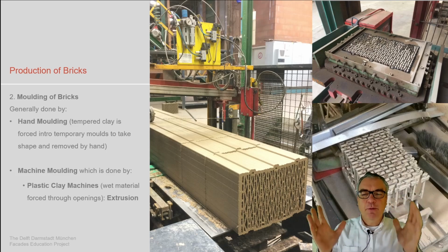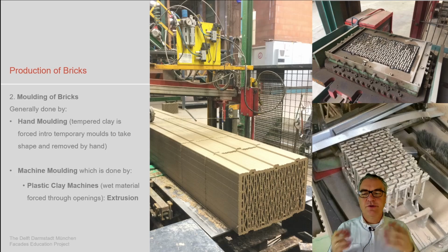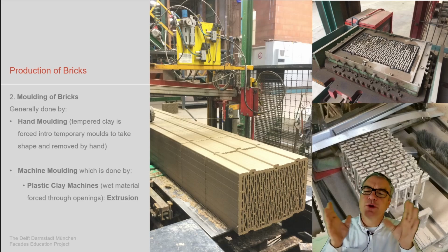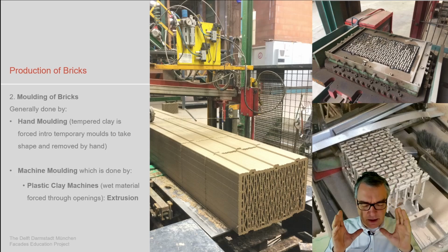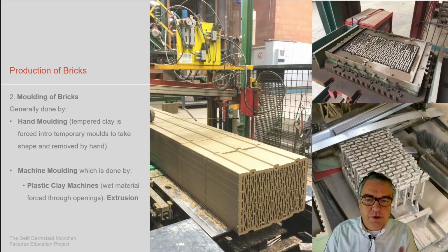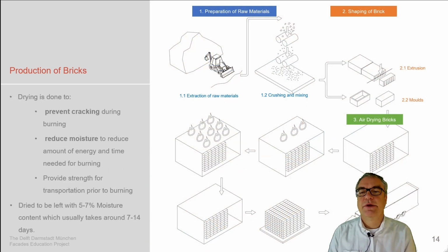Why do we have these openings? As said before, thermal conductivity, the material transports energy very well. So if you reduce the dimension of the mass of the material, you reduce also the thermal conductivity of the brick itself, which is a way to make the material a bit better insulating as a general material.